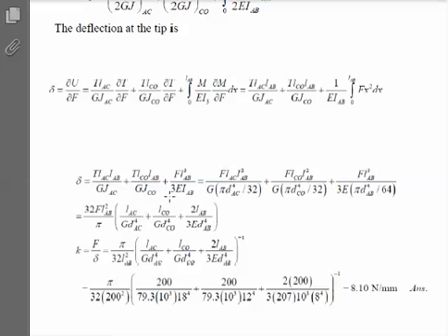We do eventually substitute that torque is F times L, already being multiplied by an L, so doing all that appropriate substitution. The other thing we substitute is that J for a circular section is pi d to the 4th over 32. We've got a diameter of the AC section and a diameter of the CO section, but we still have a pi d to the 4th over 32, and that I in this EI term is pi d to the 4th over 64.